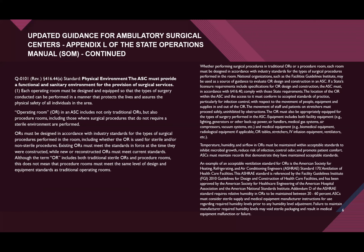And so the requirement is that law and regulation come first, then CMS guidelines, then things like CDC, and then consensus standards. The ASHRAE standard is a consensus standard, and AAMI is a professional standard. And so AAMI said, okay, fine, we'll go with the facilities guidelines. So your ORs and your sterile storage areas need to be maintained between 20 and 60%. As I'm out touring, I look at those logs, and at the bottom it'll say the acceptable range is up to 70%. And so you need to revise some of those documents if you still are looking at that as acceptable.